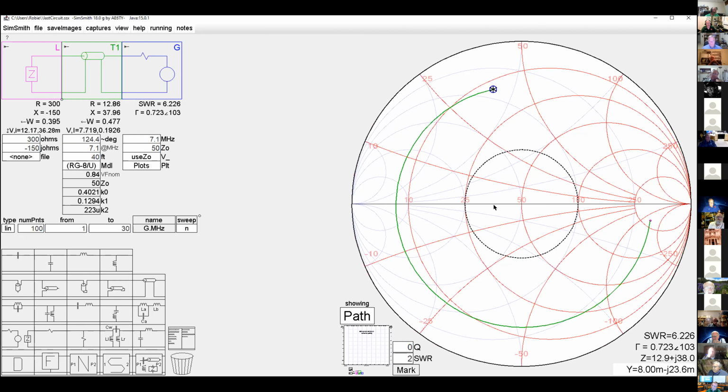And let's say this is a situation where I'm using a non-resonant antenna, and I'm going to use a tuner to match it to my rig. Tuners in general have difficulty matching real low resistances to higher values, to 50 ohms. It causes a lot of currents to flow in the components in the transmatch and the matching system. They can overheat, and you can have real problems there. It also might be out of the range of what my tuner will match. A tuner, when you buy it, says my tuner will match anything with an SWR of 10 or less. Well, that's true depending on how they measure it, but they might not be measuring it under the conditions that you plan to use it under.